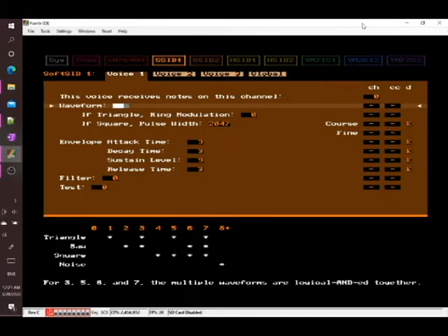This help text is showing us the meaning of the number assigned to the SID's waveform choices. I'll type in 2 for now, which is a sawtooth waveform. Now, I could have made separate checkboxes with little pictures of each waveform next to them, but it's important to represent this choice as a single number, because you have the option in this software to choose a waveform over MIDI by sending that number as a MIDI controller message.